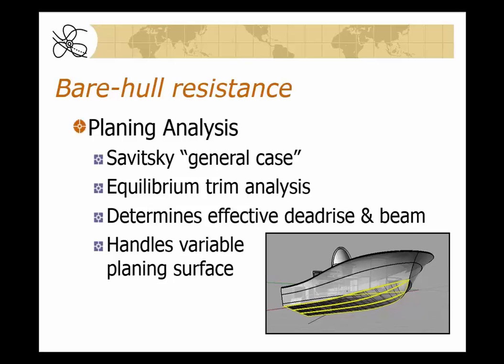So what we've done for Orca3D is that we have developed an internal calculation that comes up with effective dead rise at various station locations and an effective chine beam, or chine width of the section, and determined a comparable dead rise and chine beam that's appropriate for the Savitsky methodology. So it can handle a widely variable planing surface very, very effectively.